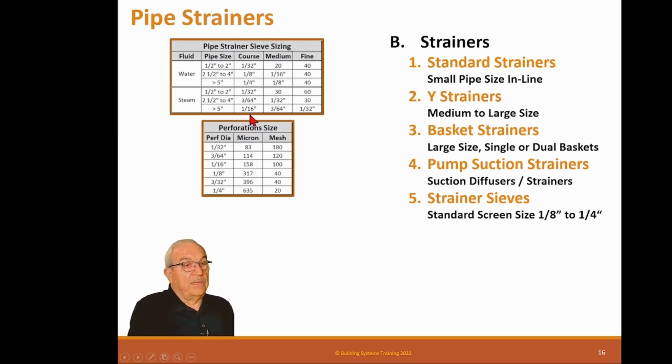Now, the thing about this is when a pump has a volute on the impeller, it sucks the water in and through velocity or centrifugal force pushes the water out those little volute holes. So your strainer must be smaller than those holes. If you put a strainer that has bigger holes than those in the volutes, the pump will get clogged. So if you have a pump that has 1/4 inch holes in the impeller where the water leaves, it could be square holes, you need to have probably a 3/16 sieve, and this chart tells you what that needs to be.